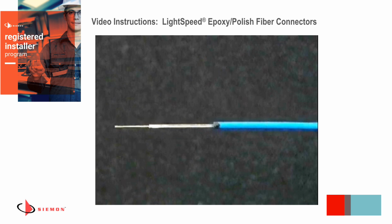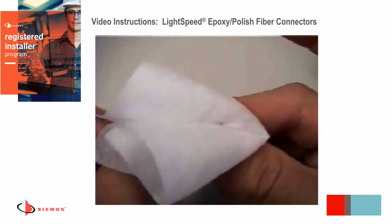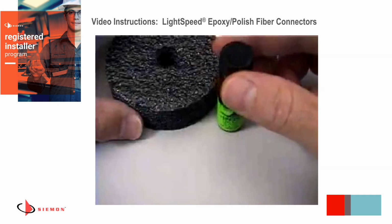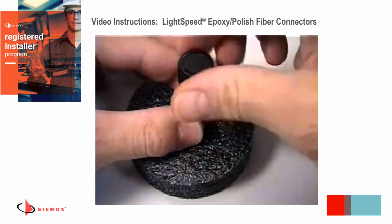After stripping, use a dry lint-free wipe to clean the fibers and remove any remaining remnants of the coating. Avoid touching or contaminating the fiber after it is cleaned. Prepare the primer bottle by inserting it into the stand provided and uncap.